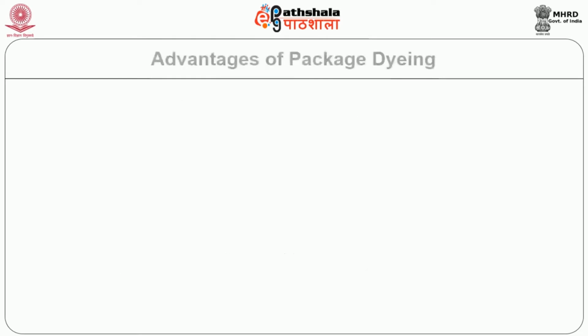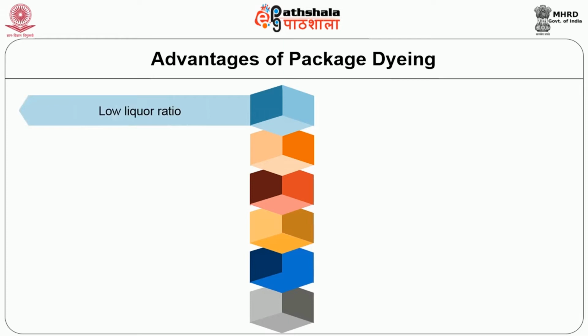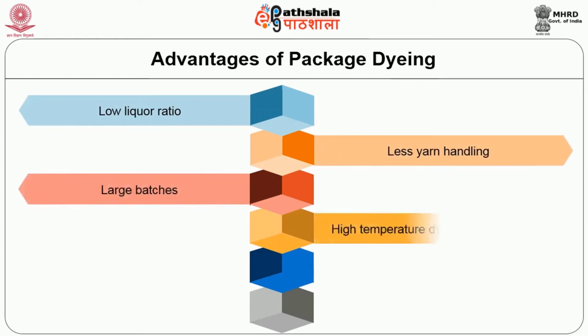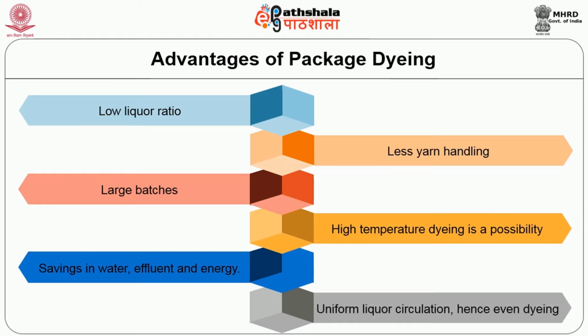Advantages of package dyeing are: low liquor ratio, less yarn handling, large batches, high temperature dyeing is a possibility, savings in water, effluent and energy, and uniform liquor circulation, hence even dyeing.